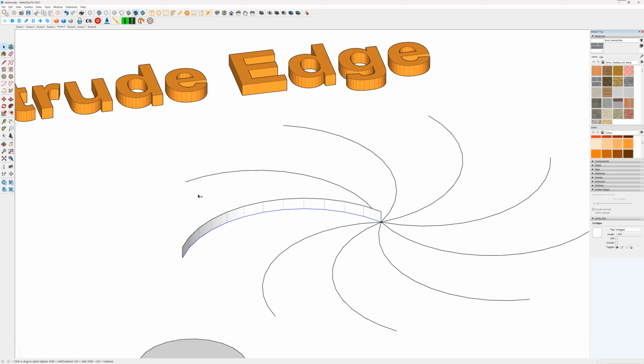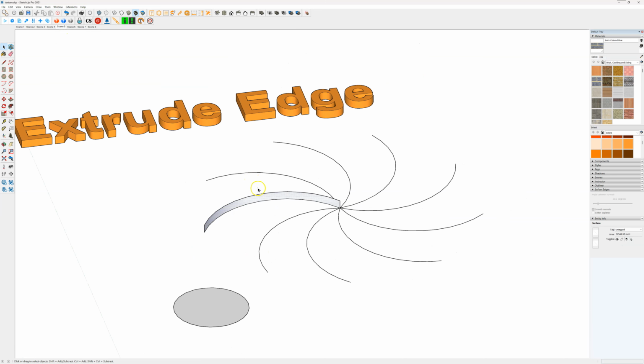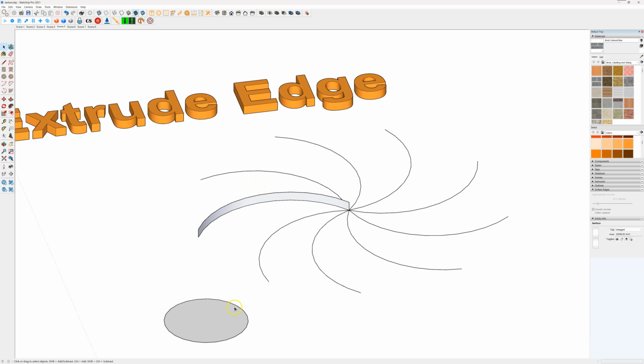I've got hidden edges switched on. In here is a camera view, hidden geometry, so Control W. So it extrudes it there without the edges. So let's do this one and extrude it up. If you press Control, it reverses the extrude.